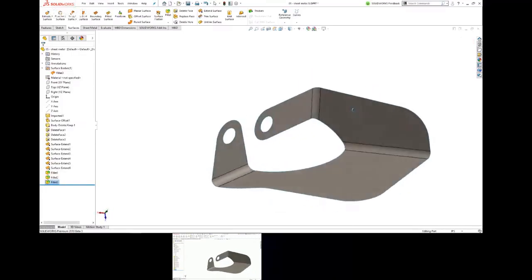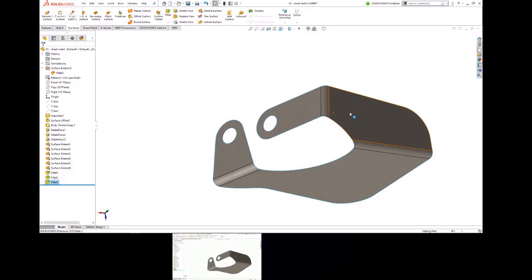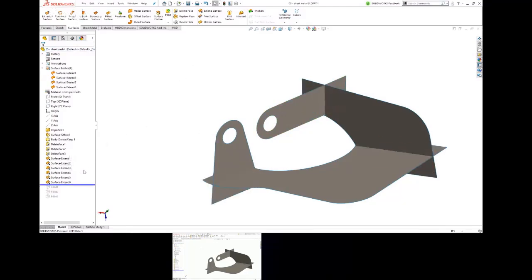So if you wanted to take off angle of that upper right one, or the top one, something different, would you have to put an eye curve or something, or a boundary? I think what I would have done first, back at the point where I have this, is use a move face or a move body command, and then I can translate or rotate that one body anywhere I want.